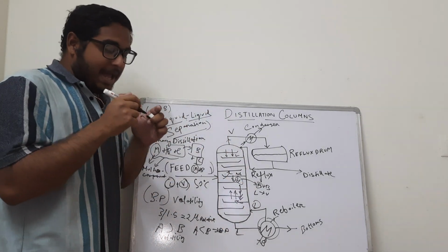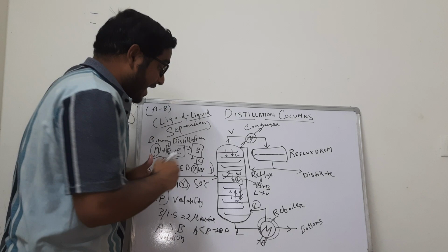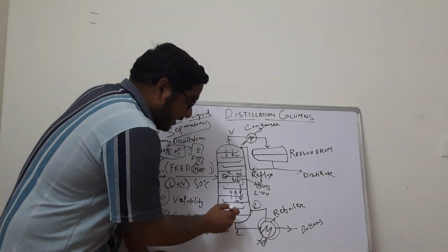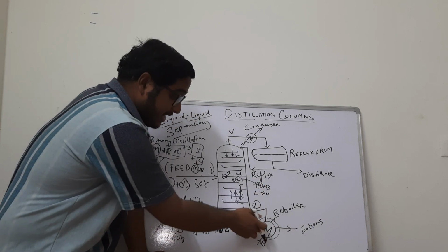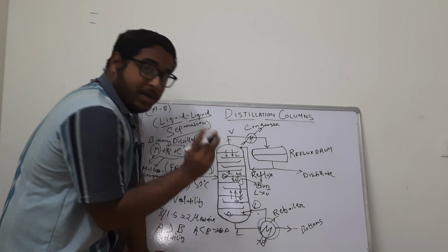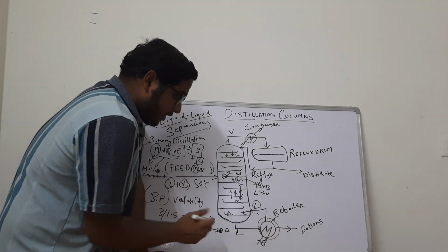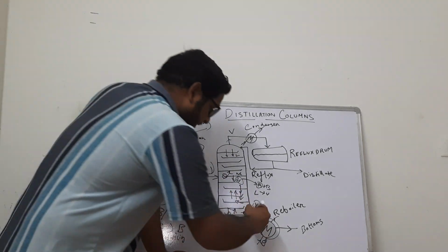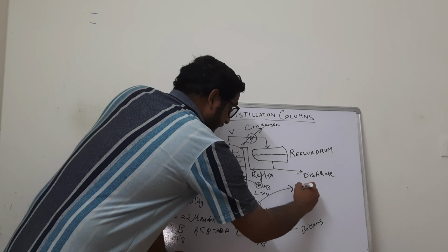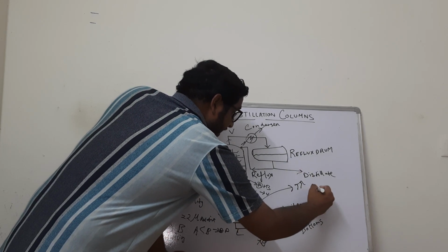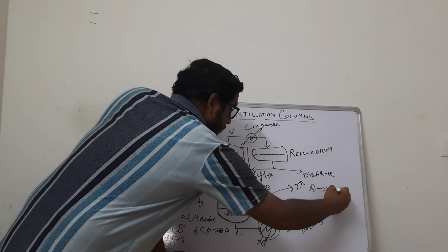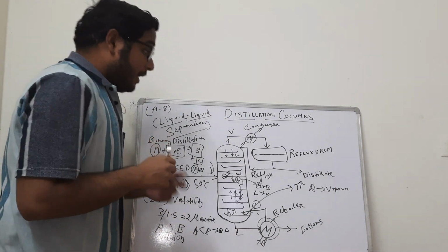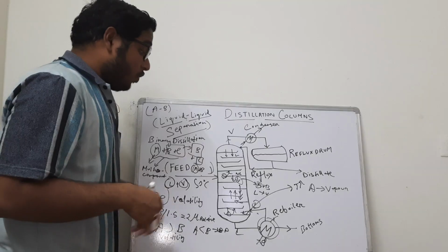So as the interaction happens, the temperature of the liquid at this plate will always be lesser than the temperature at this plate. This plate has the directly heated reflux liquid from the reboiler, and hence the temperature is going to be high. As the temperature is high, A tends to form vapor, being strongly volatile with a low boiling point.